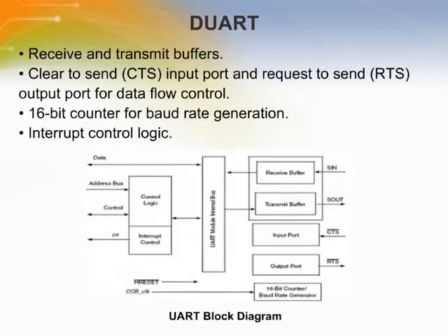The DUART consists of 2 universal asynchronous receiver-transmitters. The UARTs act independently. All references to UART refer to one of these receiver-transmitters. Each UART is clocked by the core complex bus clock. The DUART programming model is compatible with the PC16552D. The UART interface is point-to-point, meaning that only 2 UART devices are attached to the connecting signals.